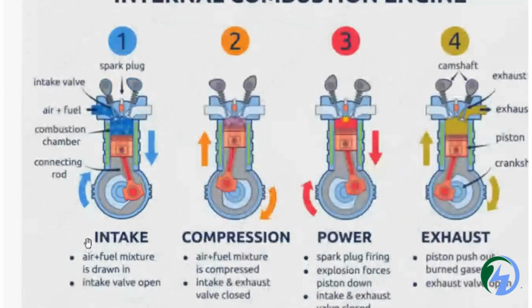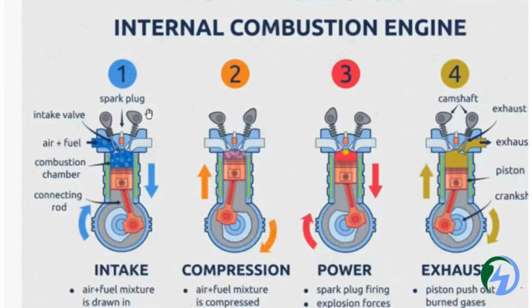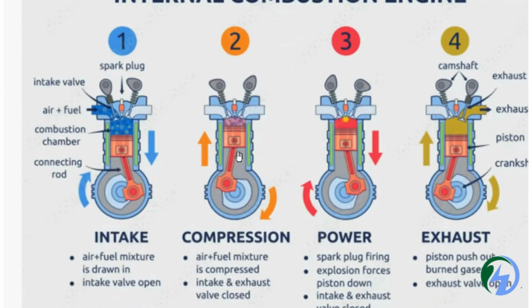So the first phase is the intake. Here the air and fuel mix is taken in, and the intake valve is opened during the first cycle. The second cycle is the compression. The piston is at the bottom. During compression, the piston moves up and mixes both the air and fuel, both intake and outtake valves are closed, and due to the high pressure and temperature, the fuel mixture creates a high